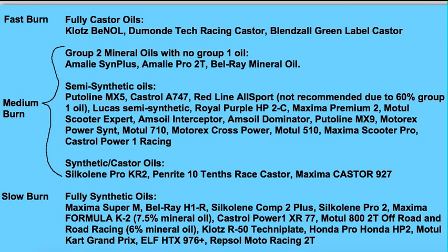This list shows how I categorize oils, from the full castor oils, which are fast burn, to the group 2 and semi-synthetics, which are medium burn, to the full synthetics, which are slow burn.